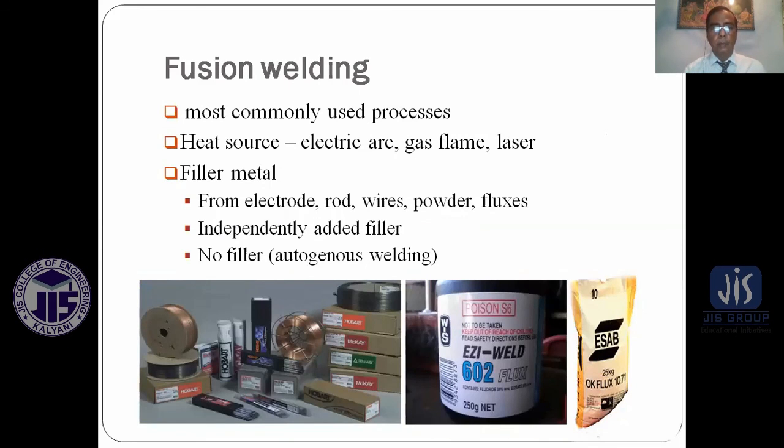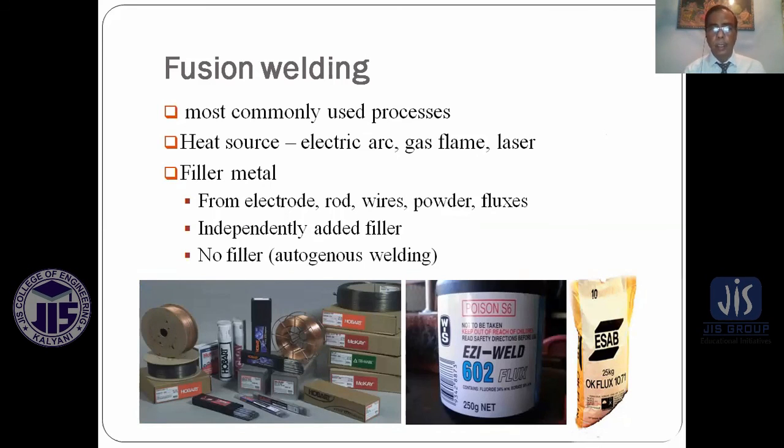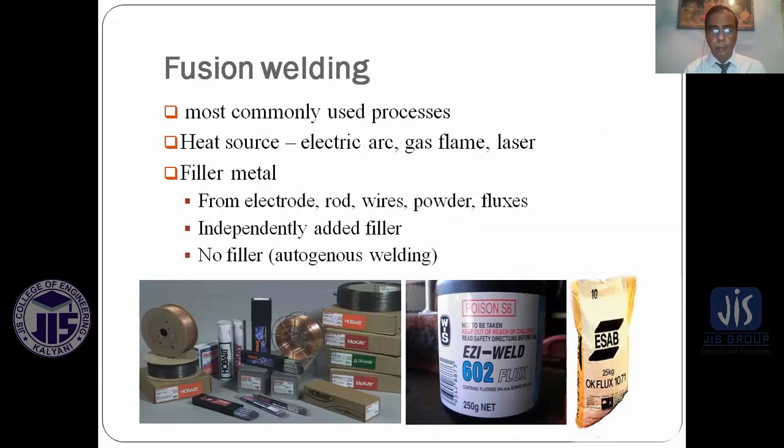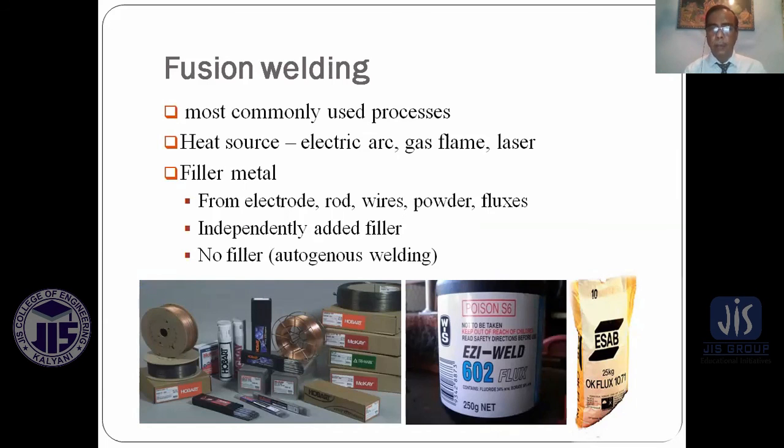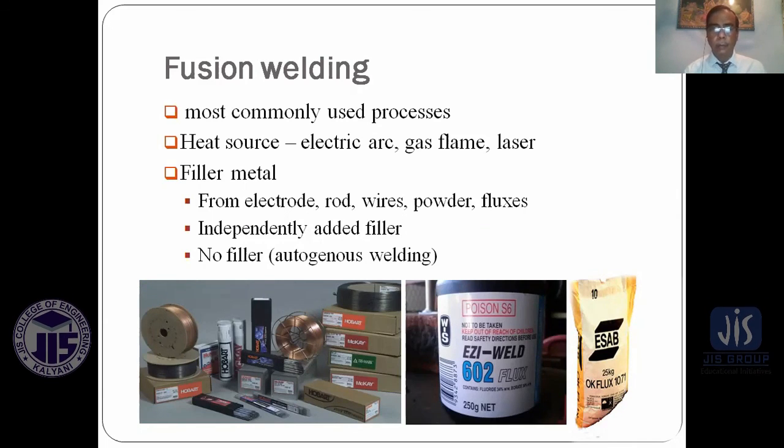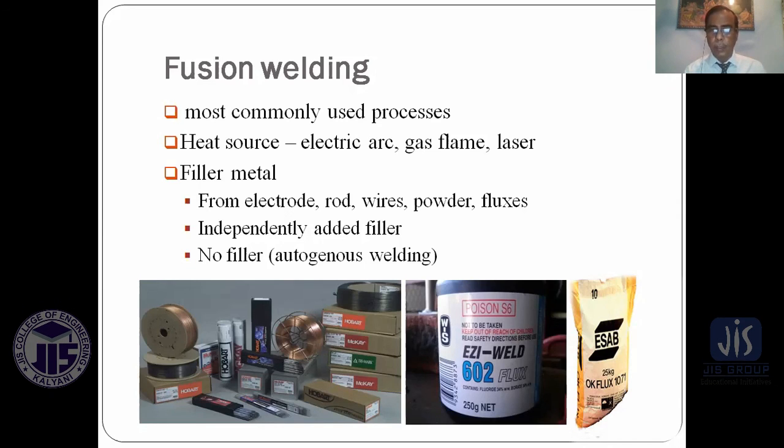Fusion welding, very commonly used processes. Heat source: electric arc, gas flame, laser. Filler material: electrode, rods, wires, powders, fluxes. Independently added filler, and in some cases no filler, autogenous welding.